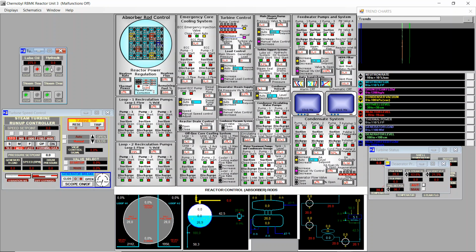If everything is fine, then you start the hydraulic lubricating system, and then open the steam drains here. We leave this stop for the moment, and once the turbine is in turning gear, we will start the steam seals. Okay, so now we go to the turbine, we reset.